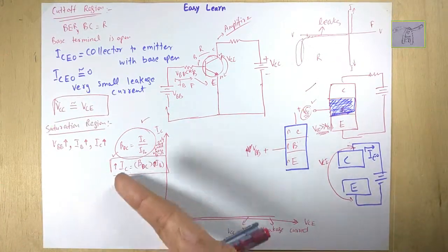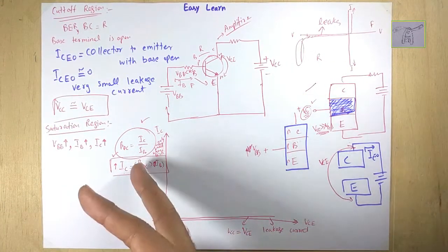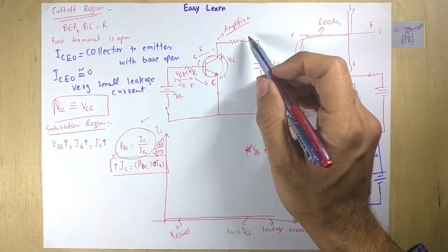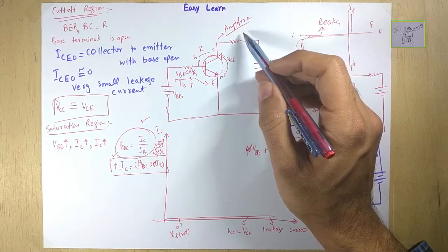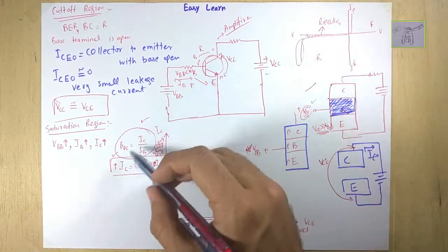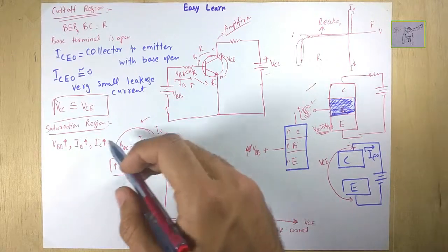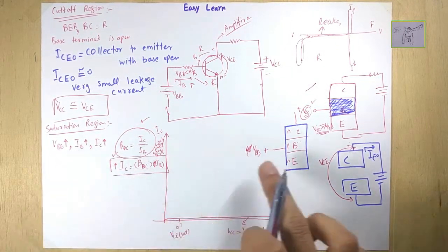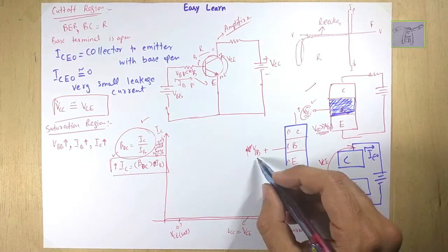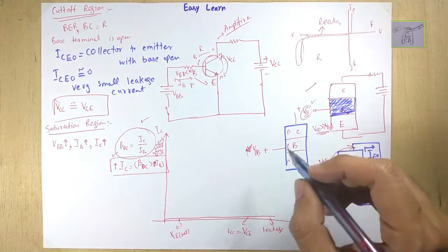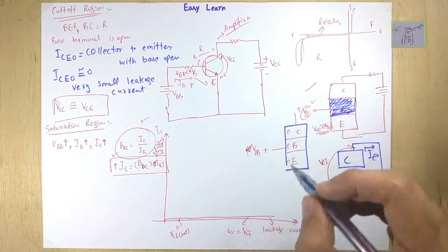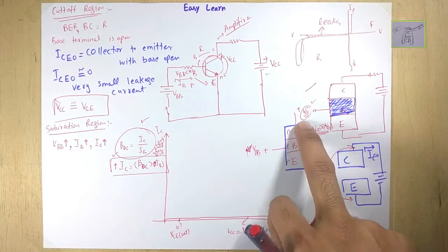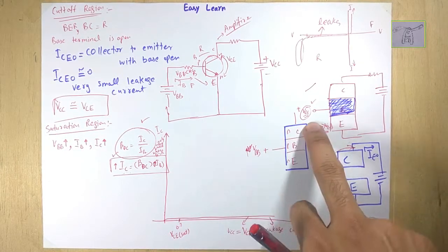And there is a formula for the gain. But when this is not in the active region and not in amplifier state, there is no gain and this formula will not be valid in the saturation region. Right now we are increasing, but we have not reached the situation when VBB exceeds VCC. When VBB exceeds VCC, then this formula is not valid.